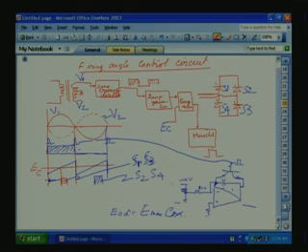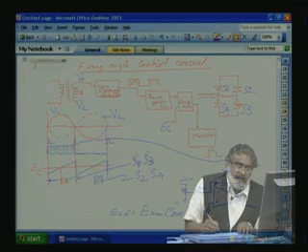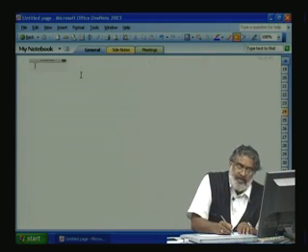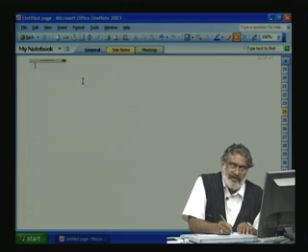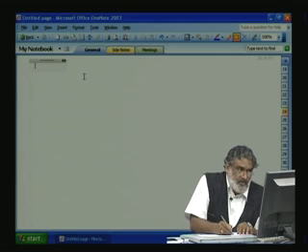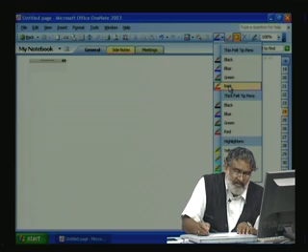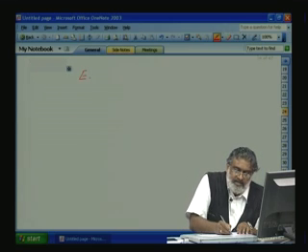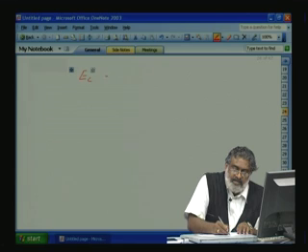This is called the ramp comparison technique. For simple power supply generation we can use it. For motor drive applications we should have linear control, so there we should use cosine comparison. We want the control voltage EC to vary not proportional to alpha, but proportional to cos alpha. Let us take our control voltage EC as E maximum into cos alpha.